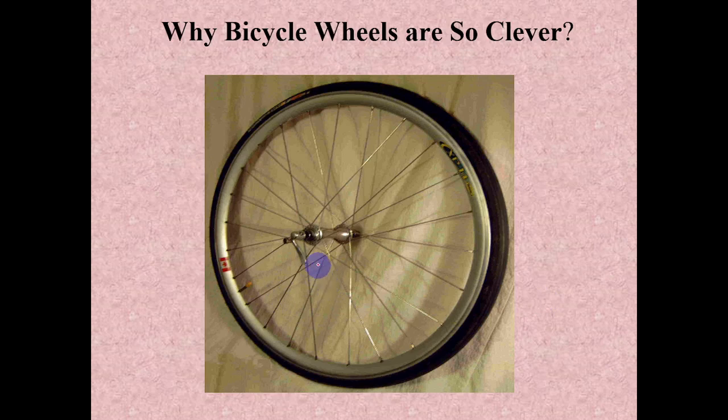If you look closely at the structural arrangement of this wheel, each spoke behaves like a column. If you consider these spokes alone, this is a column, and these ends are like pinned end conditions. And if we see this outer rim, it is a pure circle in shape, so we can assume it as a circular arch.